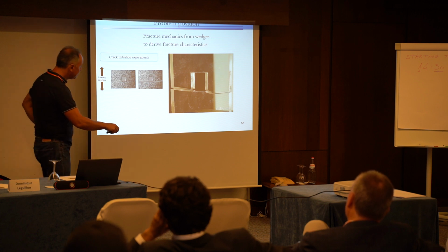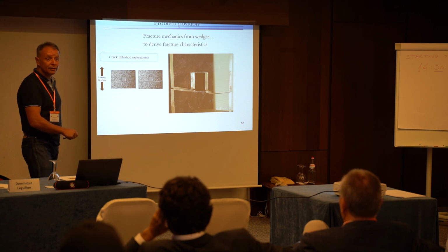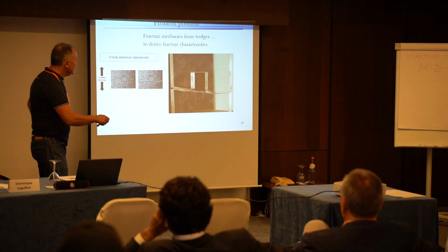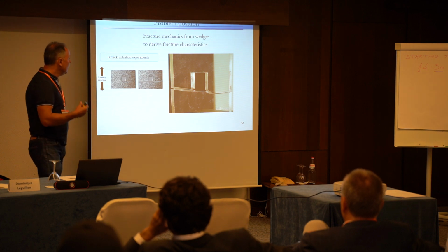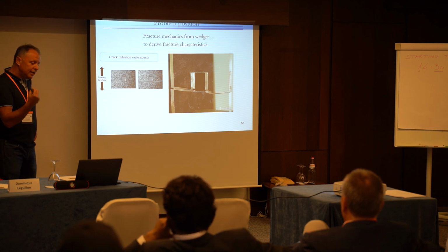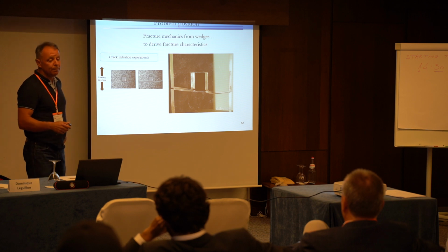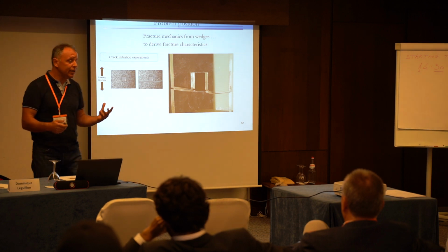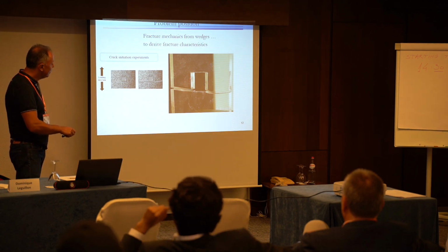What do you see here? You see that this was the first corner. There is an angle here with respect to this segment of the square angle. And there is another one slightly different on the left. So, if it was in pure mode 1, the crack would have run along this trajectory here. And distinct from what Alberto Sapora showed this morning, when you do a perfect finite element calculation, you cannot distinguish between one of these 4 corners.